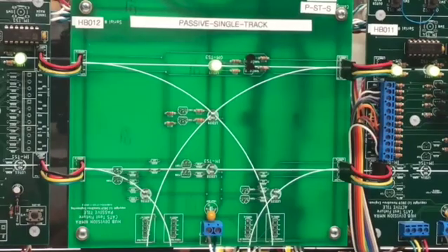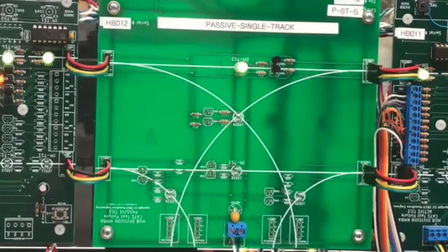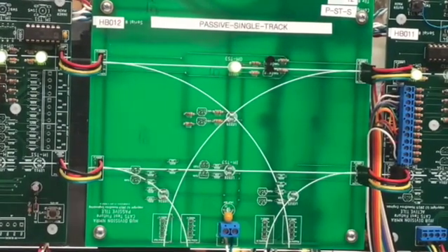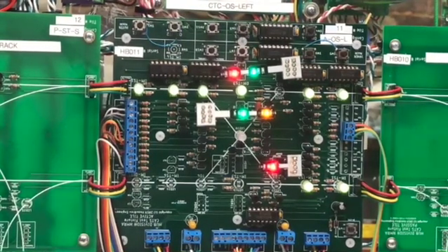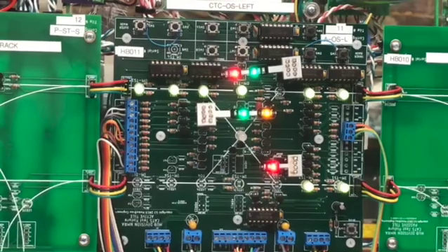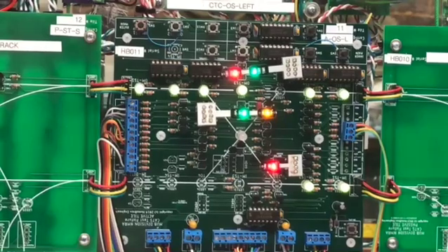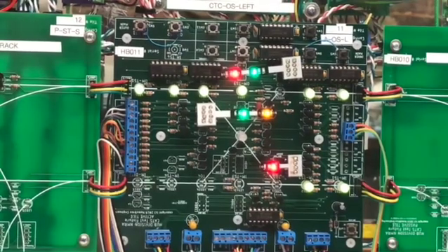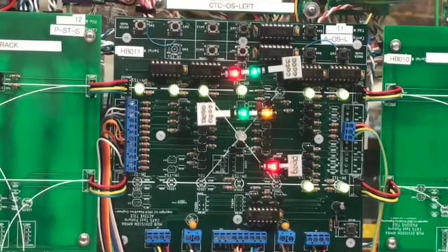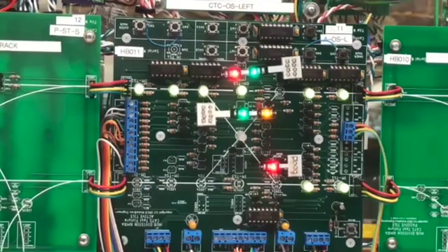This next module is another single track passive module, but this time the track segment is straight. There's only one LED which gets its occupancy information from the adjacent module. The next active module is an OS left module, so it is a single track coming in from the left, and then the turnout provides a path to either of the two tracks on the right. You'll see the two-headed signals on the top and the dwarf on the bottom. All of the block's LEDs are green, and if you look carefully at the green LED that is the third one from the upper left, it shows green, indicating that the turnout is closed or normal. The LED in the center of the X will show the occupancy of the diverging route of the turnout, which is off now because the turnout is normal.